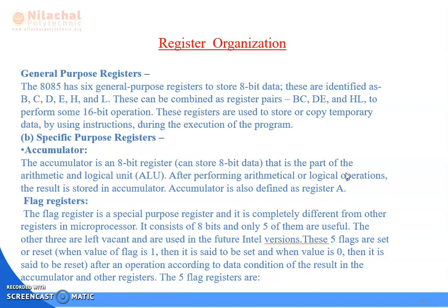Next is the special purpose register. The accumulator and flag registers are under the special purpose registers. What is the accumulator? The accumulator is an 8-bit register because it can store 8-bit data. It is part of the arithmetic and logical unit, that is the ALU. After performing arithmetic and logical operations, the result is stored in the accumulator. The accumulator is also defined as register A.